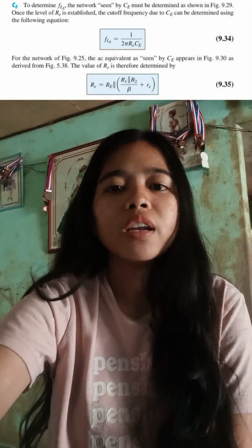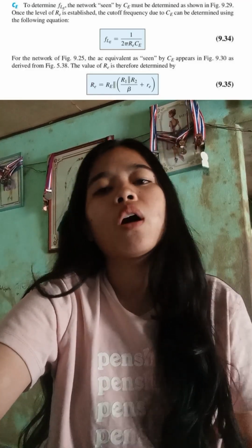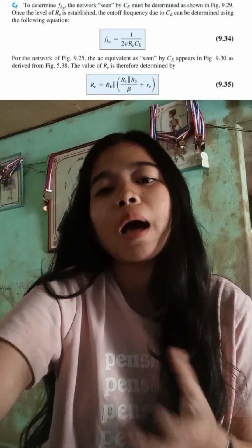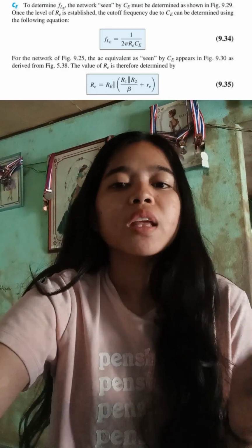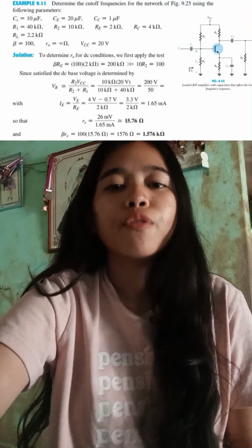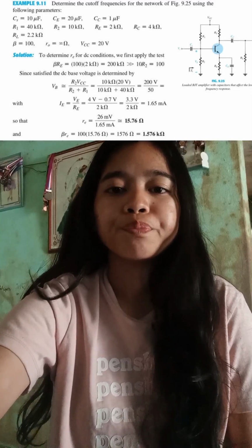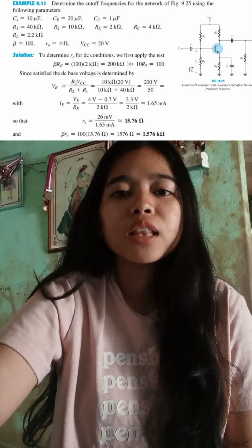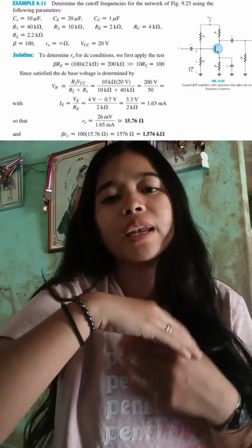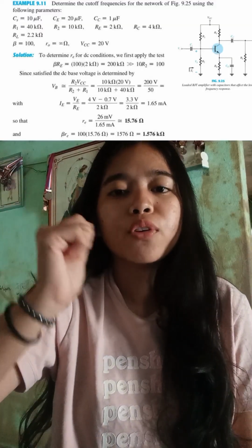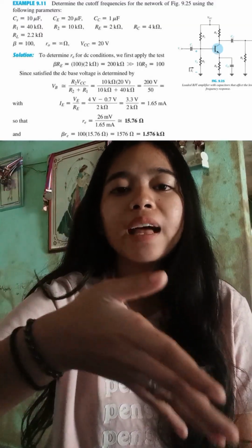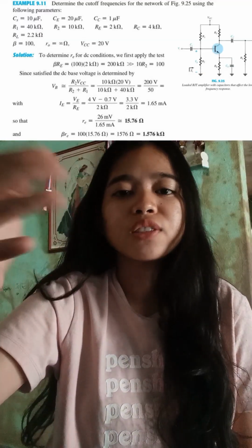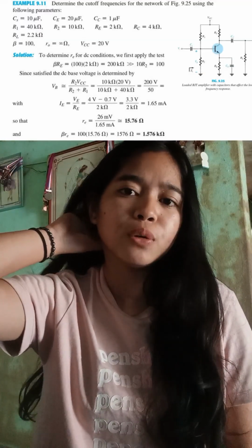So now that we have mentioned our formulas for use in frequency analysis, let us have our first example. Before we calculate any cutoff frequencies, we must first perform our DC analysis to find the transistor's dynamic resistance.